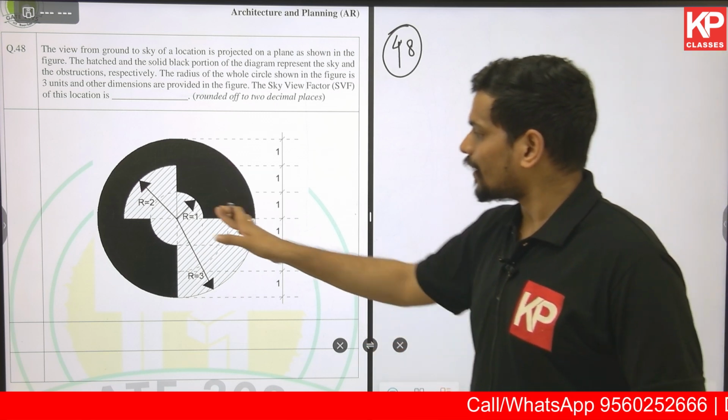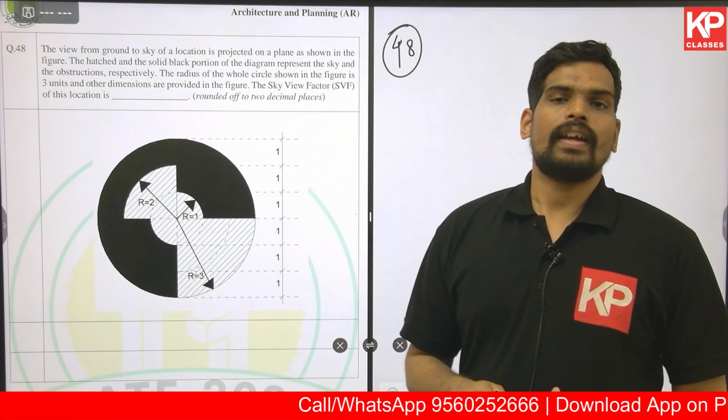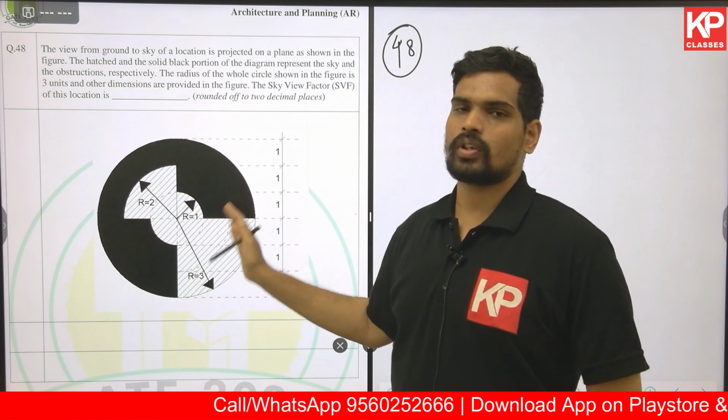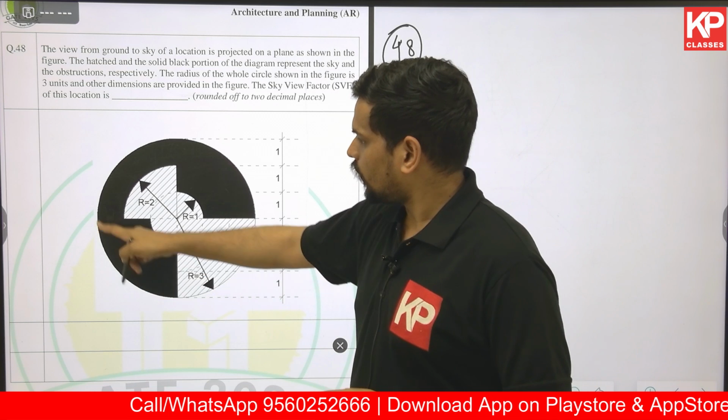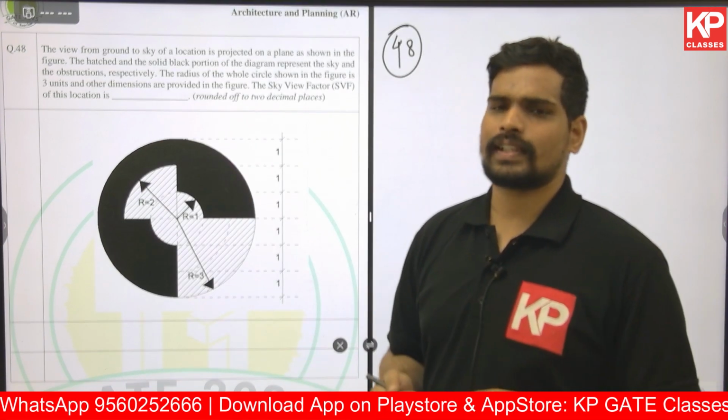So the sky view factor at a given point is the ratio of the area of sky visible divided by the overall area. So you need to see, for the complete circle, how much fraction of it this shaded portion is. That is called the sky view factor.